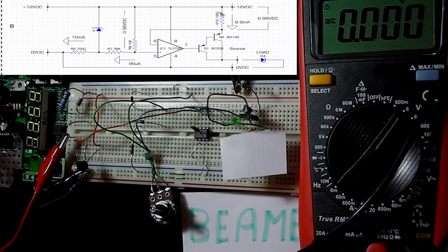If the load is very light, the constant current will attempt to always drive the output up to the compliance voltage, and whatever circuit you might have might not agree with that higher voltage. It might blow your circuit up. So it's always worth bearing in mind with a current source, it's good to have adjustability on the compliance voltage so that you know exactly where you are and you're not going to cause damage to your load.